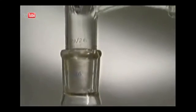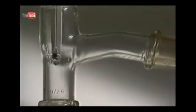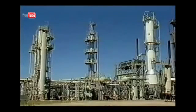This lifting and dropping back down slowly puts each component aroma chemical of the essential oil at a different level or band in the column. This is happening simultaneously with each component aroma chemical of the mixture within the essential oil. Having reached as high as they can, they drop back and are warmed again. Now all that has to be done is the column is tapped at each level to remove the target aroma chemicals. Some preparation of the material may be made to facilitate better separation. Geranium oil, for example, is saponified, that is, reacted with an alkali to produce a soap prior to fractional distillation.